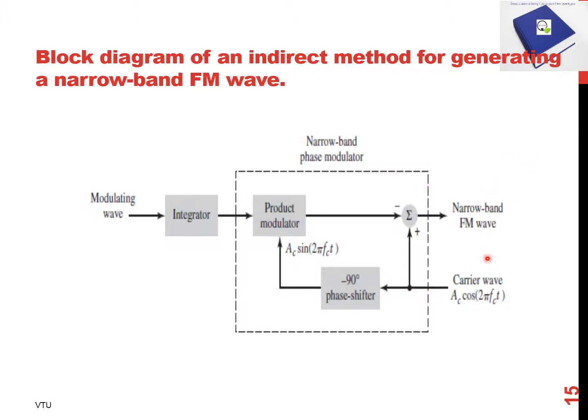Another method: wideband FM can be generated from a narrowband FM wave by passing it through a nonlinear device and then through a bandpass filter.